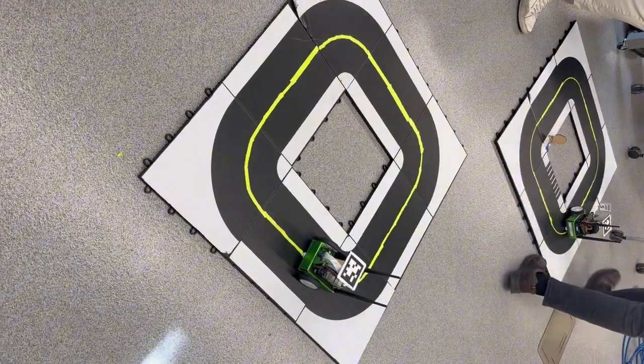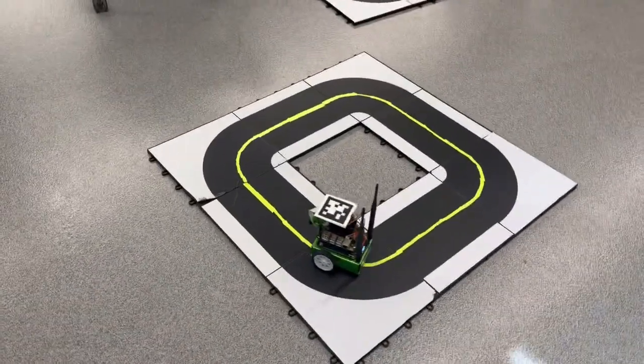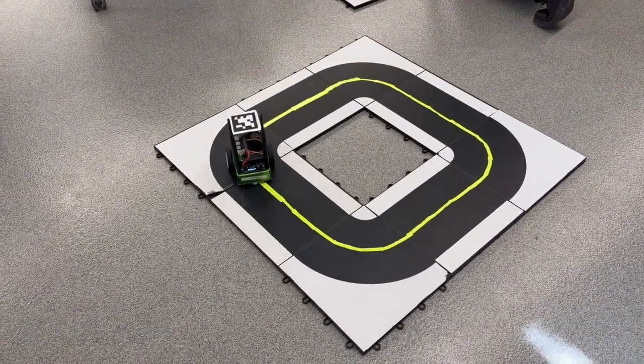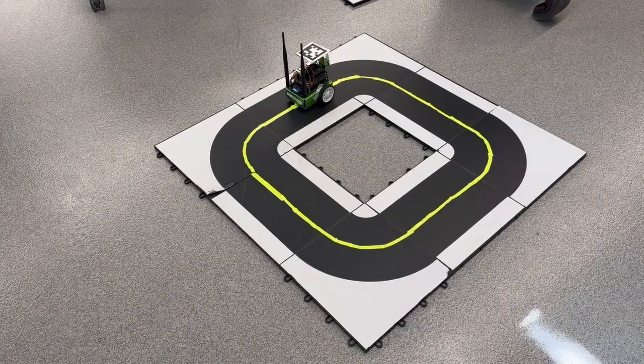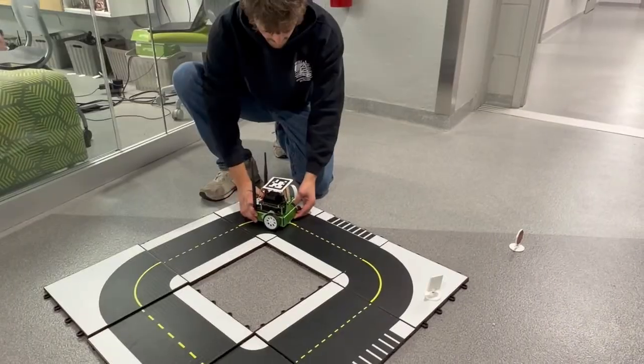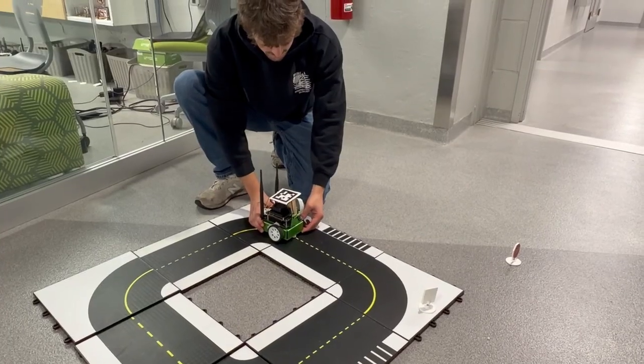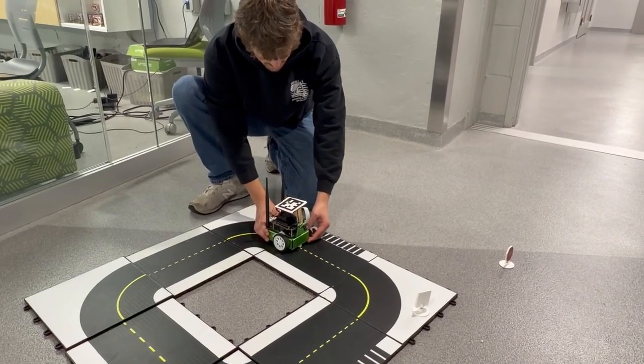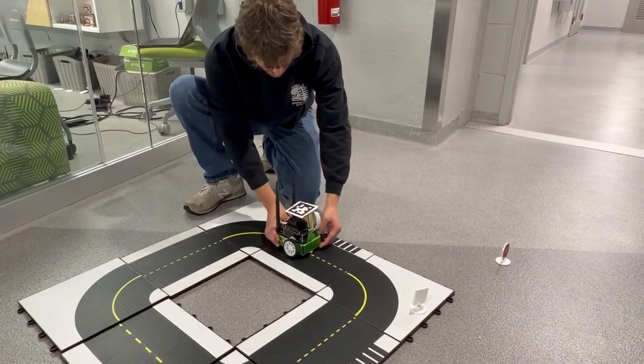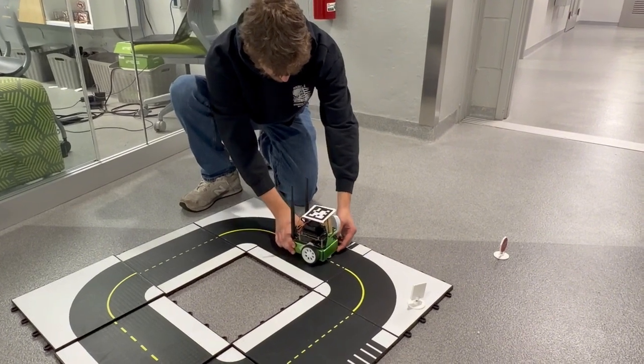We then needed to train the JetBot to identify where the center of the road was. To accomplish this, we adjusted the HSV values to ensure it could pick up the center of the line on the mats. Next, we used NVIDIA's interactive classification tool to collect data and train a predictive model using a transfer learning method to classify different road signs.